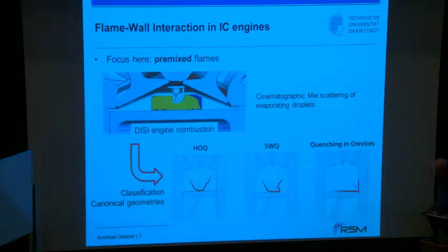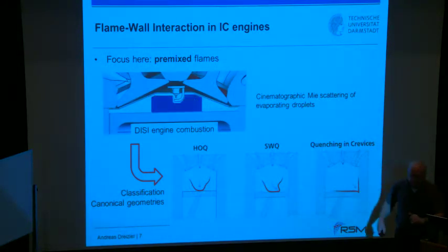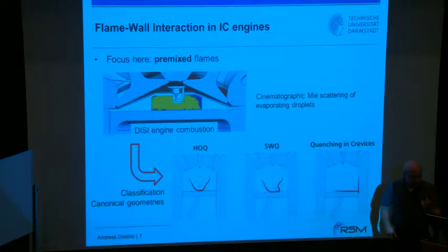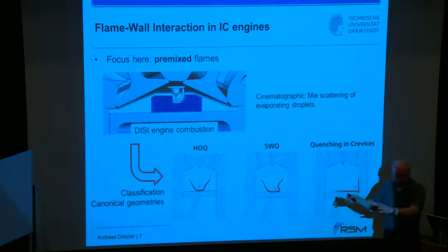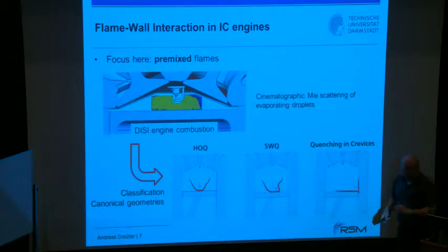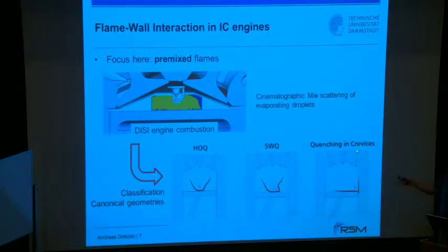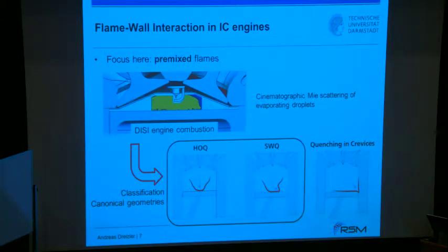But what we are now doing is, instead of continuing that research in the engine, as I said earlier, when you have a little understanding of the problem, not directly go into the complex geometry, do it with simplified geometries which are motivated by the real one. And the motivation comes here from the early phase of flame wall impact, where you have head-on quenching. I explained that, where the flame ideally in that concept is propagating just perpendicularly against the wall, or sidewall quenching where it creeps along the wall. Of course, you as well then have quenching in the crevices, which needs then a different setup, which I will not detail today. So we will have a closer look into head-on and sidewall quenching.